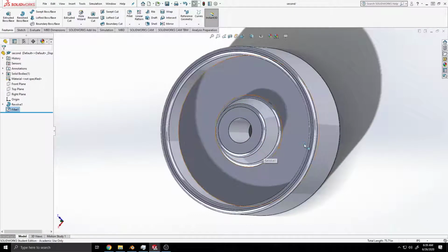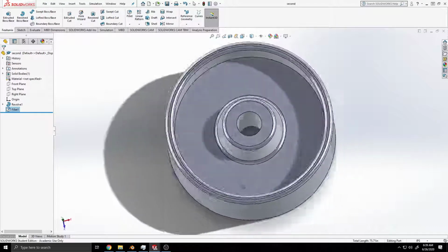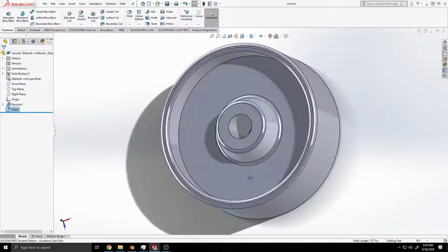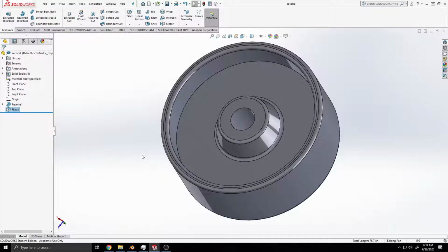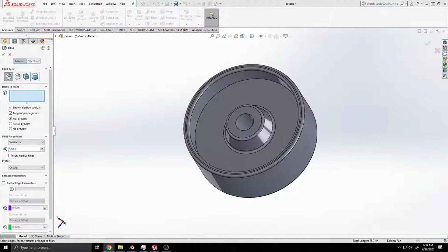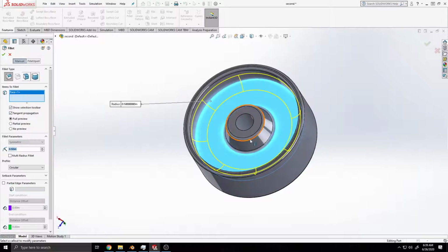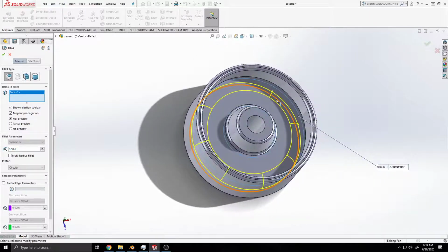Let's add a different sized radius. Go to fillet and now set the radius to 0.5 and select this edge here and use the X-ray capabilities to find that edge underneath it and click on that so we don't have to rotate again. Hit the green check.